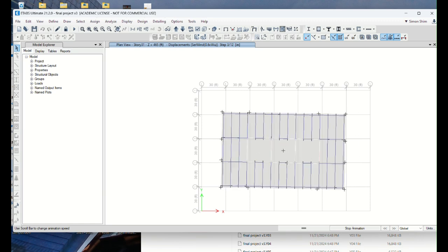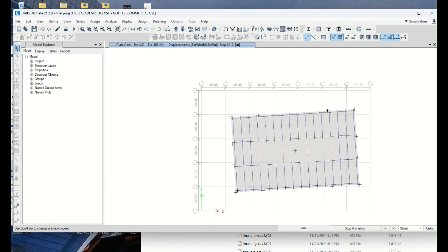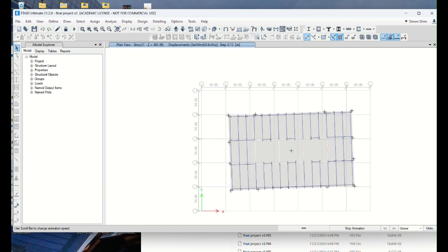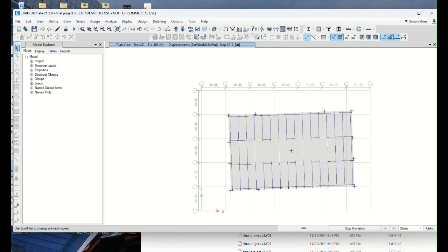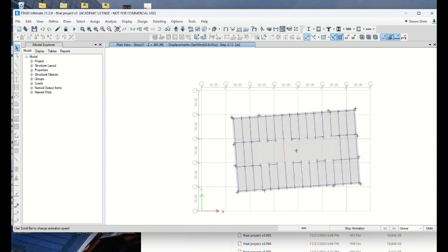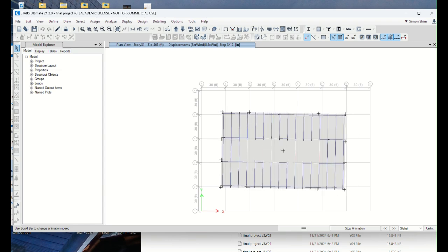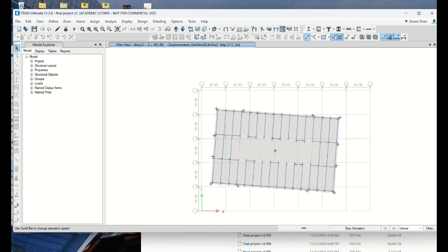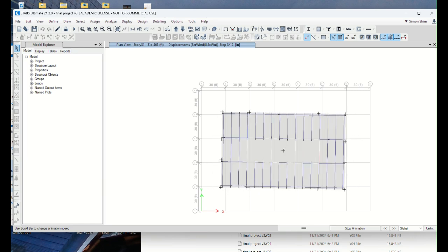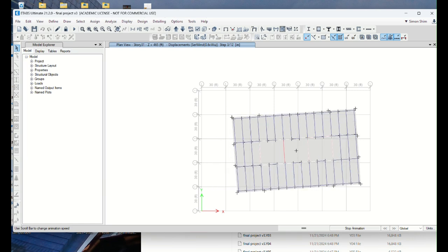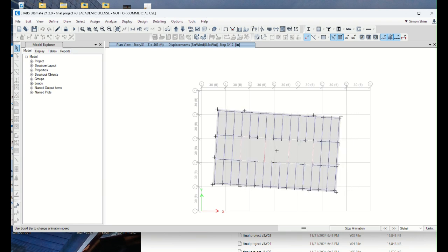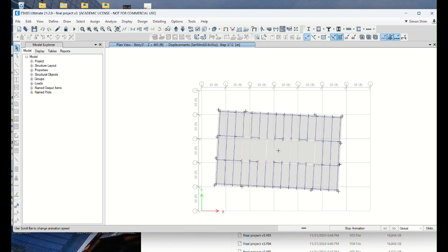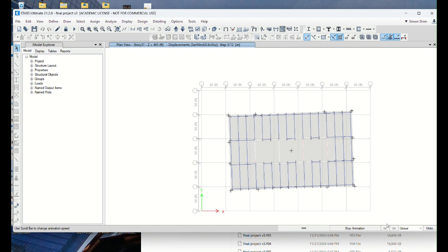Torsion. Because the load in the X direction is offset 15%, so that in wind 3 it generates wind from 15% off the center. You see that? Because these are all the load cases based upon ASCE 7, the point is that ETABS generates 12 cases to drive this effect. In the Y direction, you can see the same thing, you can guess.